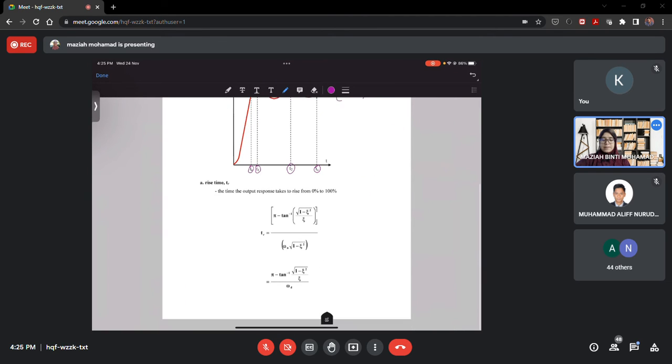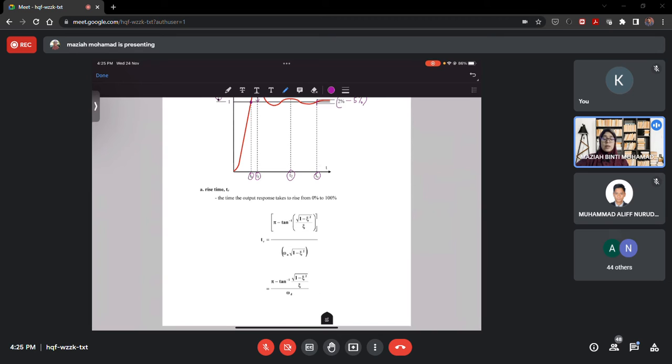All right. So that is the indicator that we look at, meaning by calculating the parameters of rise time, maximum overshoot, T1, T2, and settling time, we'll be able to explain the behavior of the system. We can compare a system based on how fast it reaches the final value, the rise time. We can compare based on the maximum overshoot. We can compare based on the settling time.